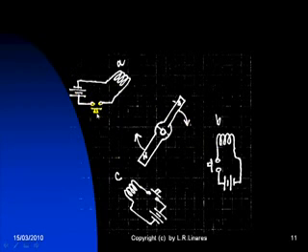Now, we push the button associated with coil A, current flows, coil A becomes an electromagnet, and the bar will try to align itself with the coil, will start to rotate, and when it's about to be aligned with it, like so, we let go of the button. The current is cut in the coil, the electromagnet is no more, and inertia will carry the bar over.